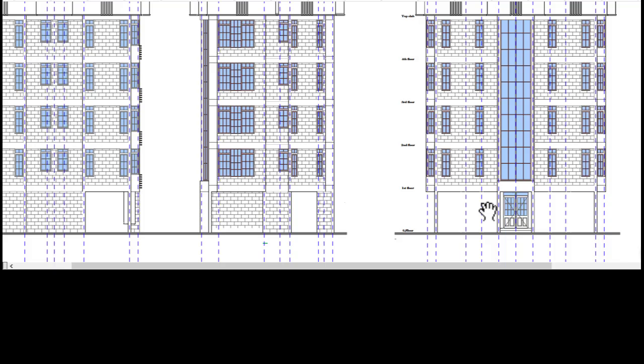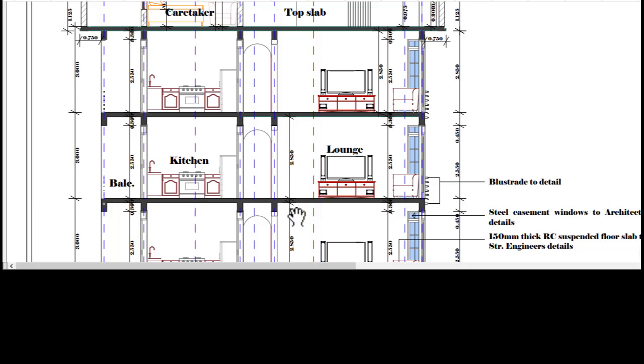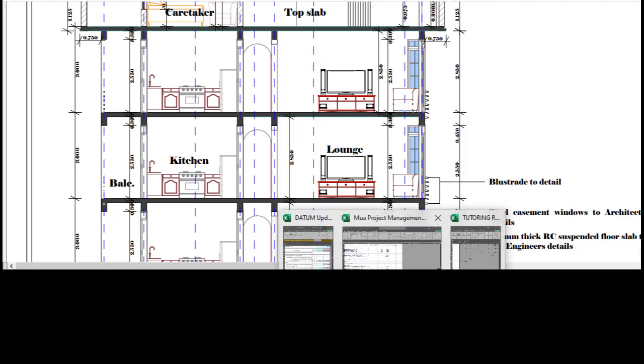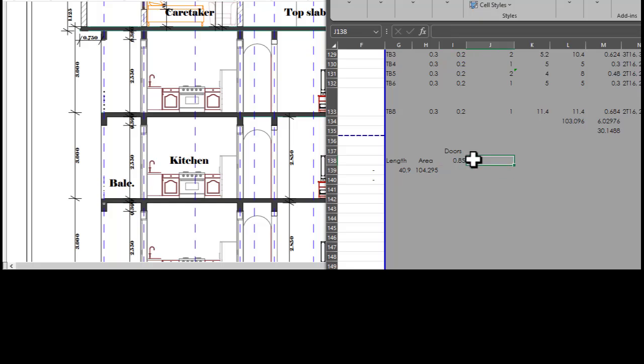But then in my region, doors are always made, some of them are standard, of course, in terms of height. So a height of about 2.4. Of course, the height that was provided in the section was showing 2.55, but then doors, most of them are at a height of around 2.4 meters. Okay, so this is 2.4 meters. That is the first door that we have dealt with. So the other door, let's see if there is another.